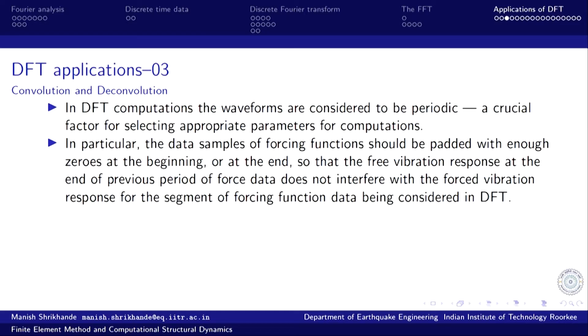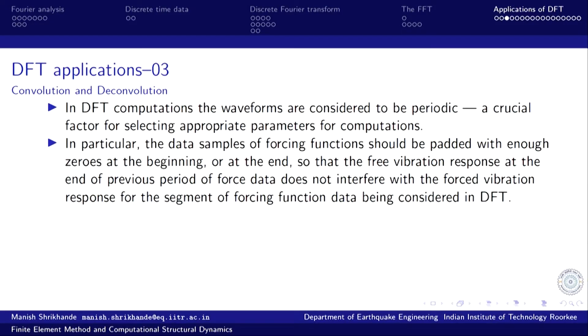In particular, the data samples of the forcing function should be padded with enough zeros at the beginning or at the end or at both ends, whichever is preferred, so that the free vibration response at the end of the previous period of force data does not interfere with the forced vibration response for the segment of forcing function data being considered in the DFT.